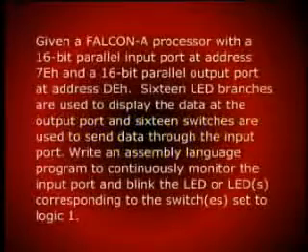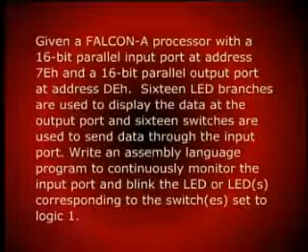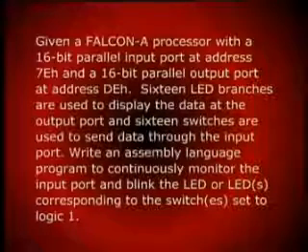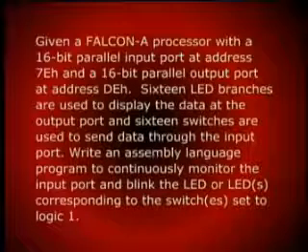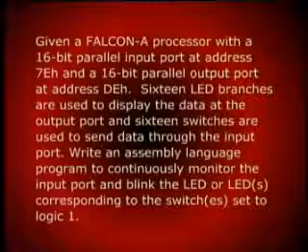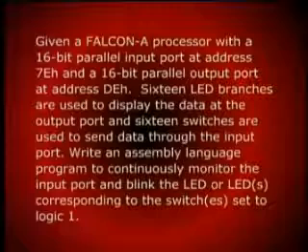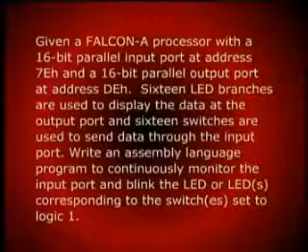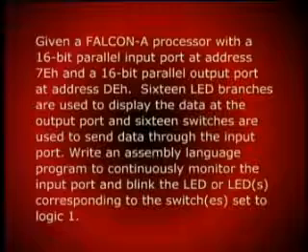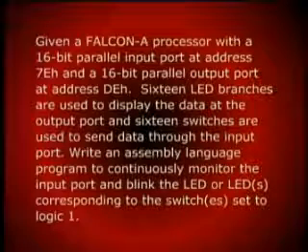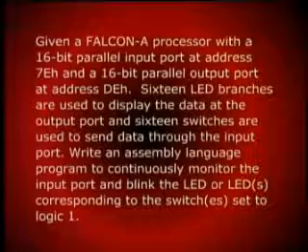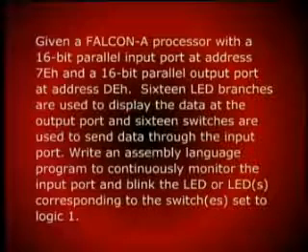As we have said, we are given a Falcon A processor with a 16-bit parallel input port at address 7E hex and a 16-bit parallel output port at address DE hex. 16 LED branches are connected to display the data at the output port, and 16 switches are used to send data through the input port.